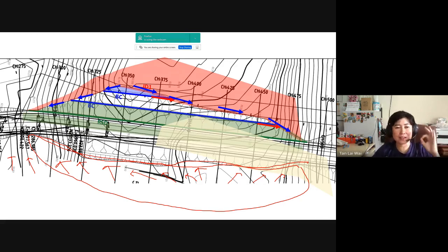So you need to do a site survey, go to the field, look at what is there. Sometimes, for example, you have a pylon, you know, this tiang electric, right? That blocks your way. So when you design this road also, you need to make sure your alignment is out of that pylon pathway. So you have to be careful. So that is the importance of your site survey. Clear? Clear, doctor. All right.